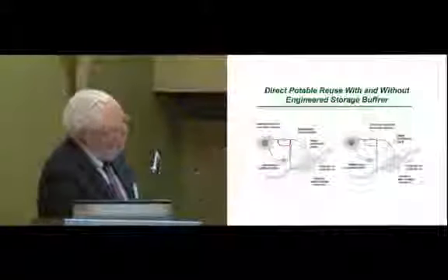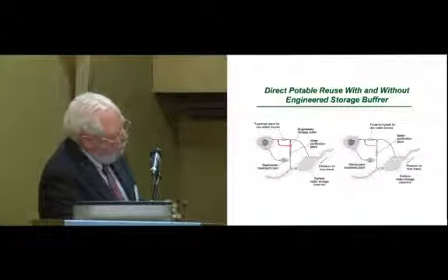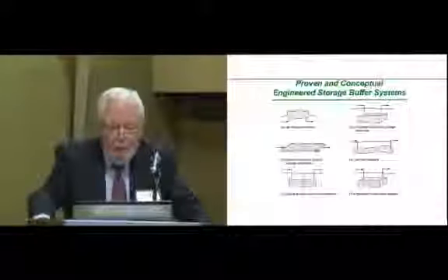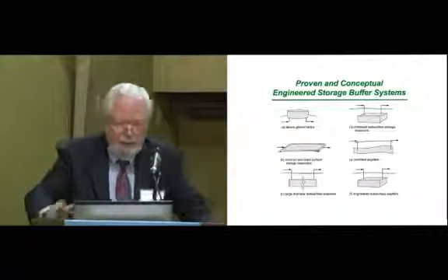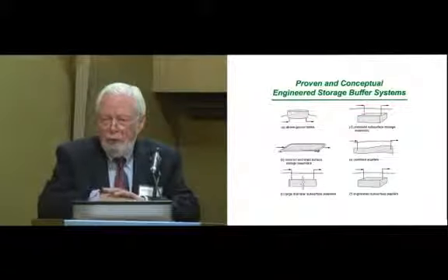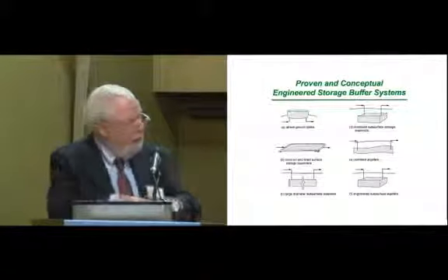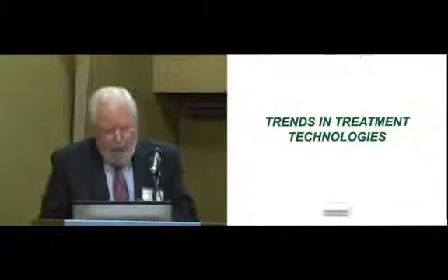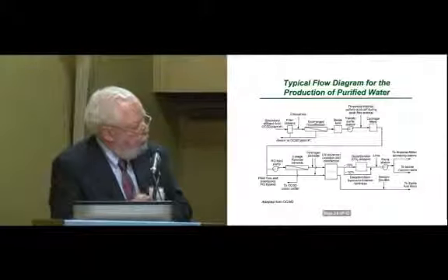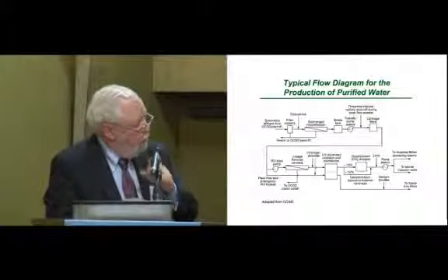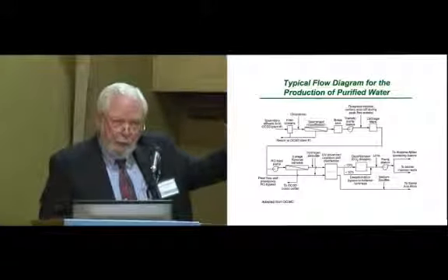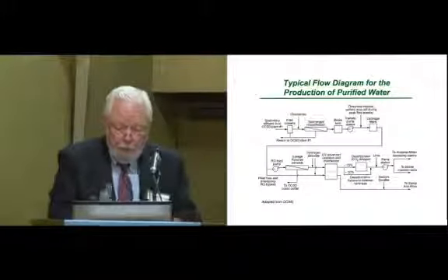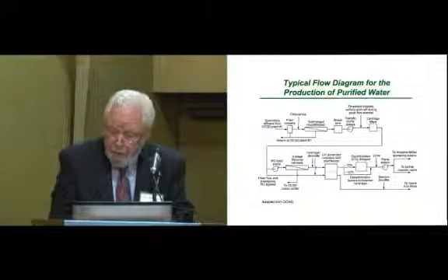So here we're talking about direct potable reuse with or without an environmental buffer. Now, when we look at environmental buffers, they could be of any type. Surface water storage, groundwater. Only your imagination limits you in terms of the design of the engineered storage buffer. When we talk about trends in treatment technology, the bar has been set pretty high by the Orange County Water District. Here's their diagram. I'm not going to go through this. You're all familiar with the various processes. But microfiltration, cartridge filters, reverse osmosis, advanced oxidation.